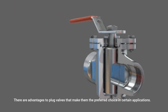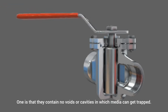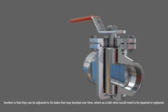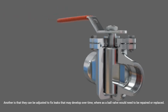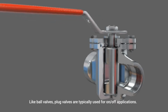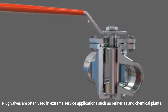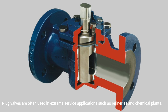There are advantages to plug valves that make them the preferred choice in certain applications. One is that they contain no voids or cavities in which media can get trapped. Another is that they can be adjusted to fix leaks that may develop over time, whereas a ball valve would need to be repaired or replaced. Like ball valves, plug valves are typically used for on-off applications. Plug valves are often used in extreme service applications such as refineries and chemical plants.